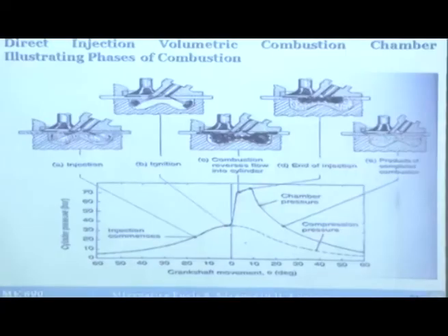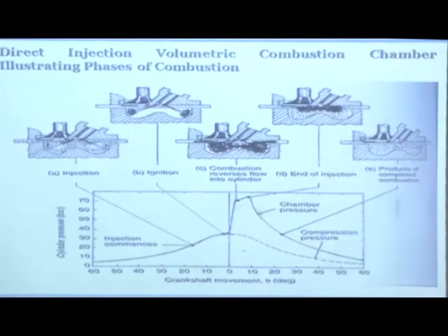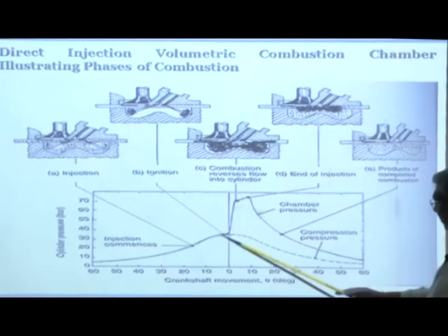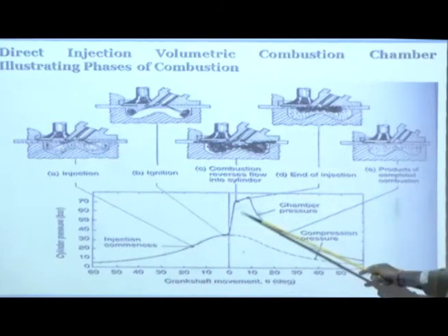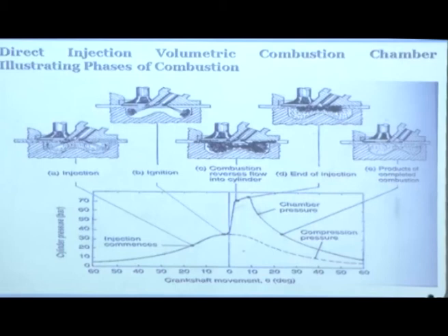So this is the motoring diagram. Motoring diagram means you are just compressing the air and expanding, no combustion taking place. Okay, so this is the motoring diagram, and this is the firing diagram. Firing diagram means you put the fuel. Now let us see when things are happening.